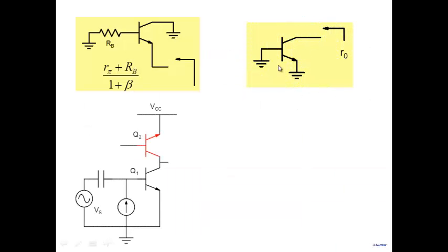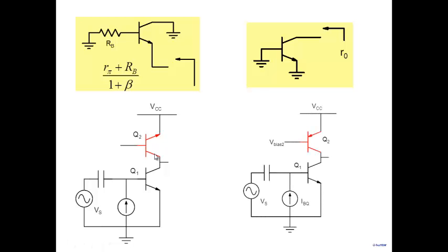Can I do that? I connected the collector here. Can I do that? Obviously not. It's pointing here. The current has to flow in the same direction. I can't do that. I need to connect the collector at this particular point. But if I just take an NPN transistor and connect the collector here, then the emitter would be here, and it doesn't make sense because we want the current to flow here. You're right. So what we need to do is connect it in this manner.